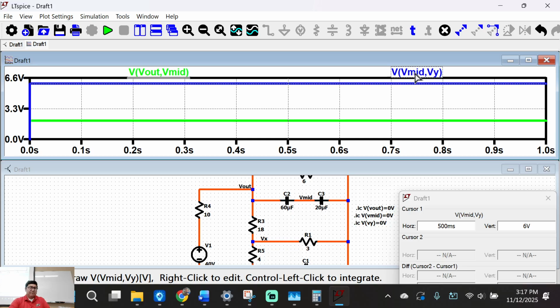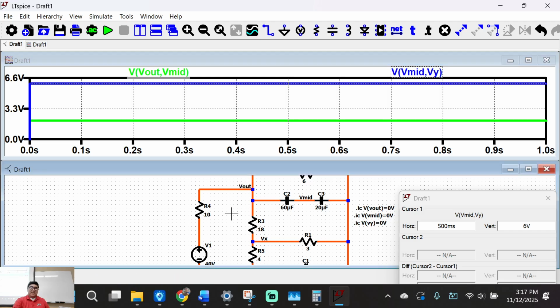With capacitors, yeah. When you're doing transients, most of the time, well, it depends. It's good to set everything to 0 charge because capacitors initially have no charge. There's nothing in them. They're just buckets of empty water. But you have to set that up first. Some circuits, it's not that hard, especially when you have a V out and a ground that are established. But this right here, it didn't know what to do. So the computer just said, I'm just going to calculate what makes it easier for me.